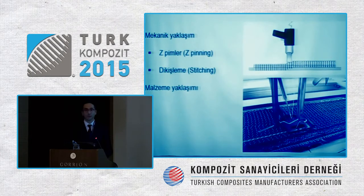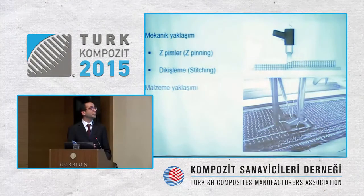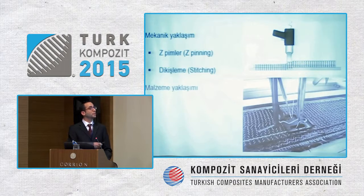We have mechanical approaches like Z-pinning and stitching. When it comes to Z-pinning, this is applied before curing. An ultrasonic device is used, and the pins may be steel or composite.